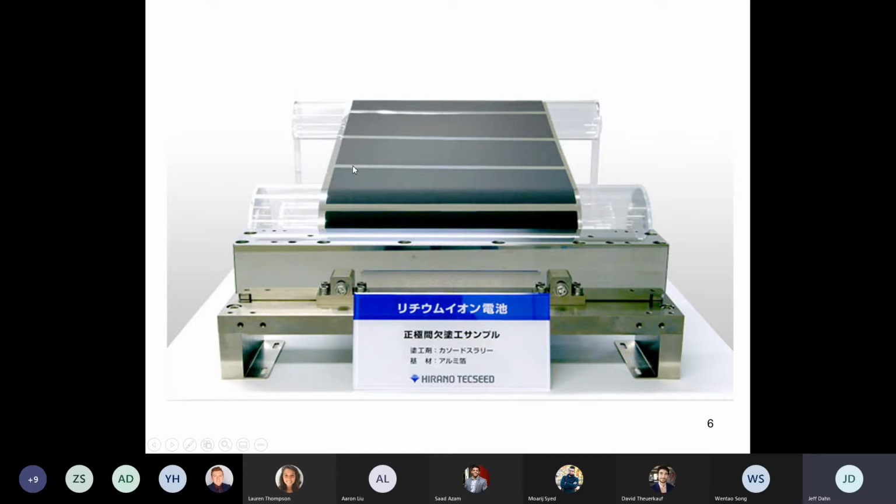Well, cleaning the foil was done with a brush, not too aggressive. You didn't want to damage the foil. But still, you can imagine you're brushing this electrode powder with a brush, you get dust all over the place, and you have a vacuum nozzle there sucking up the dust. But some of that dust in principle could end up lying on top of the electrode if you don't get all of it. And those dust particles could cause penetration through the very thin separators, leading to safety issues.